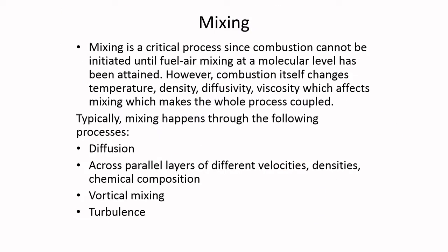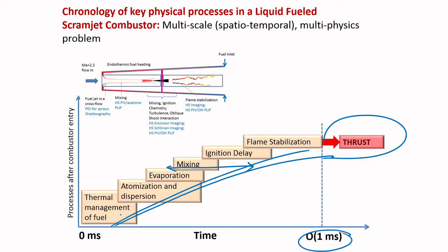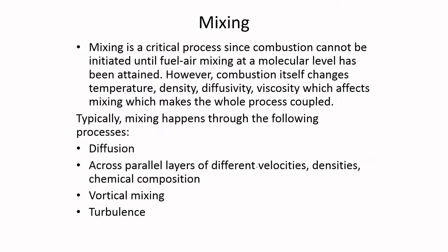So we will go into mixing. Mixing is a very important process inside a scramjet, and often it is the process that takes the most amount of time. Mixing is critical because we all know that combustion cannot happen, it cannot even be initiated, unless fuel-air mixing at a molecular level has been achieved.